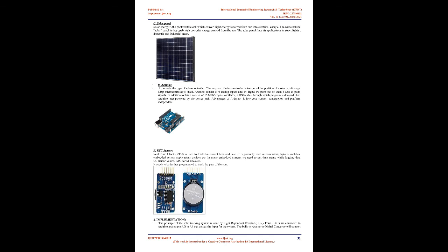But LDRs are voltage-based, and tracking systems are very sensitive to voltage. An accurate and very sensitive technique is the use of light-to-frequency conversion due to the fact the frequency is directly proportional to irradiation. That means it is directly proportional to power, primarily current. The LTF also contributes in synchronizing between both the pilot and panel without the need to use external switches. On the energy side, and in some case, it has the opposite effect, where more energy is consumed by the driving motors and mechanical gears than the generated energy. Unfortunately, both problems were not addressed previously.